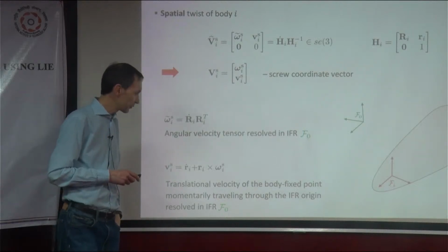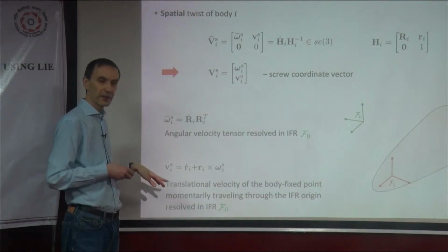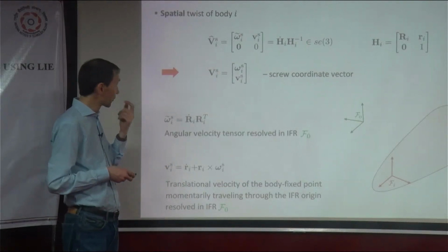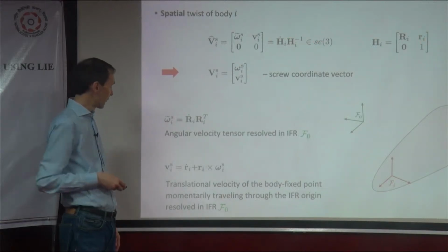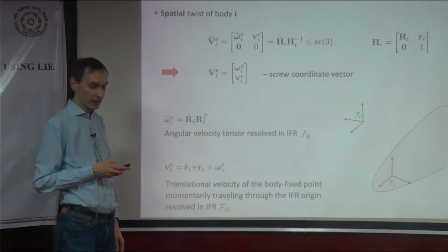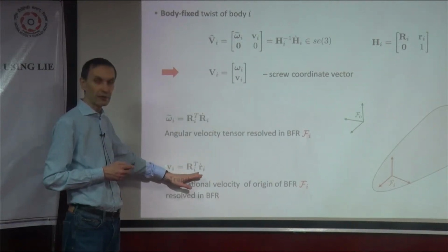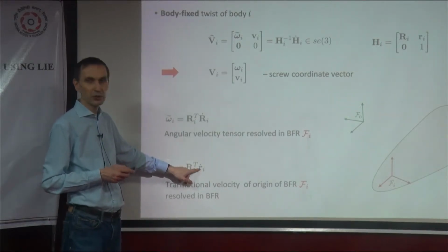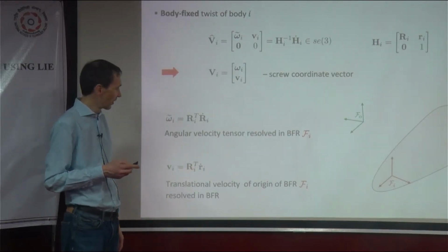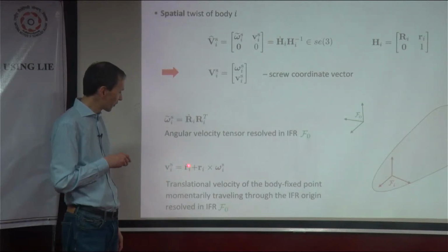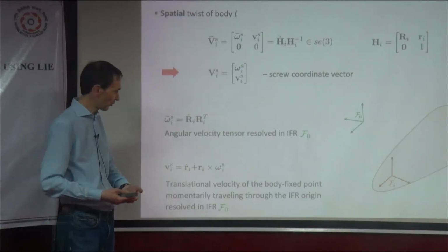What is more mind-boggling, or a bit puzzling maybe, is the linear velocity, because it's the same. Just do the computation, plug this in, and what you get is this, right? Remember the obvious notion of linear velocity: I have the r dot, which is of course the velocity, and I transform it to the body frame, then we have this. What you get here is different. Of course, there's no rotation matrix involved in this because we express everything in the space fixed frame.